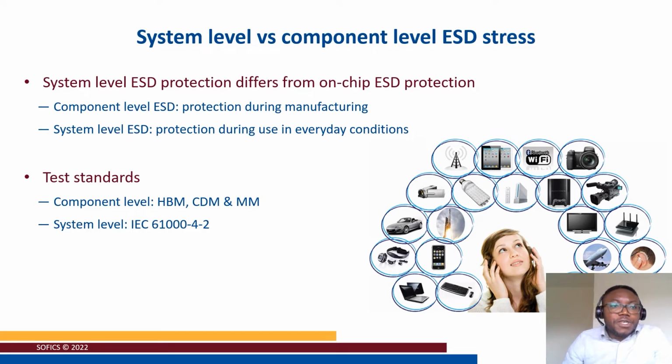On-chip ESD protection is aimed at preventing IC failure due to handling by machines or people during manufacturing and assembly processes. Once ICs become integrated into packaged chips and boards, the on-chip ESD protection structures are not so active anymore. The electronic devices are not completely safe from ESD though, as external ESD events can still cause IC failures.